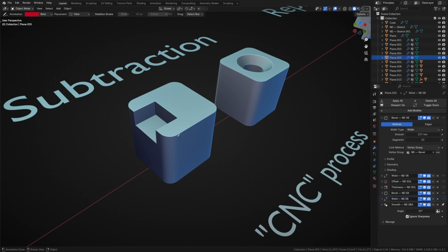Before demonstrating the concept of subtraction, can you apply any of the principles we've already covered to simplify this shape? Take a moment to think about it. It doesn't seem likely, does it? Any plane you can identify doesn't produce the qualities we're after. We could remove the fillets from the edges, but we'd still be stuck with a broad 3D form. As a side note, sometimes this is all you can do, but we can do more in this case.